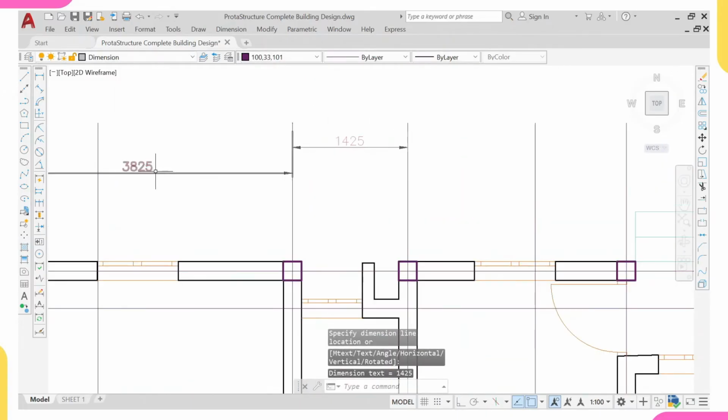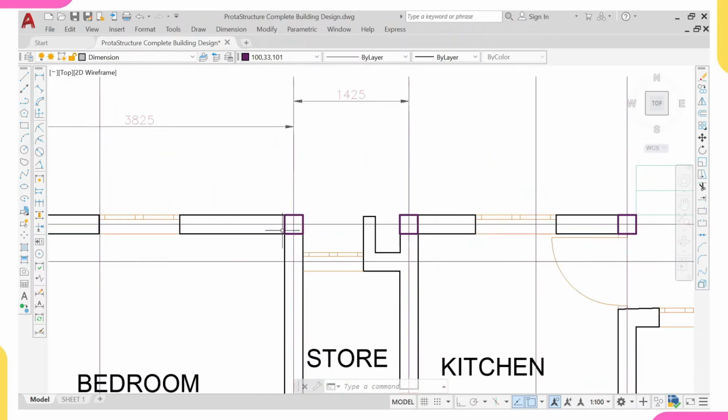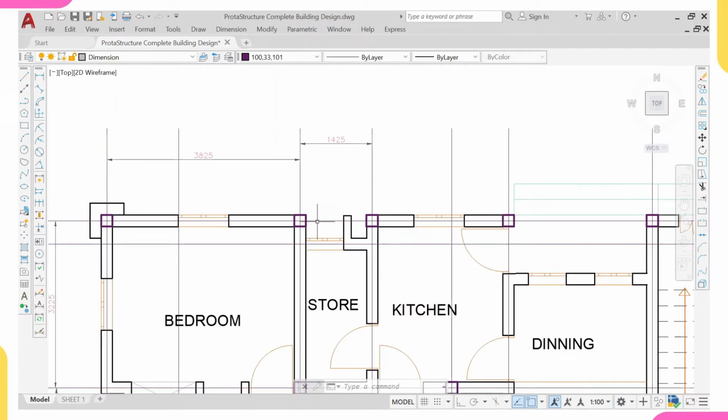So I'll also check from this point to this point. If you check now, this plus this is less than 6 meters, but I'll leave this column here and also leave this column here. The reason is because here is a void, this is a void. That's the reason why I'm leaving this column here and here. Assuming right now I'm having a beam running through, I will remove this column. You understand?